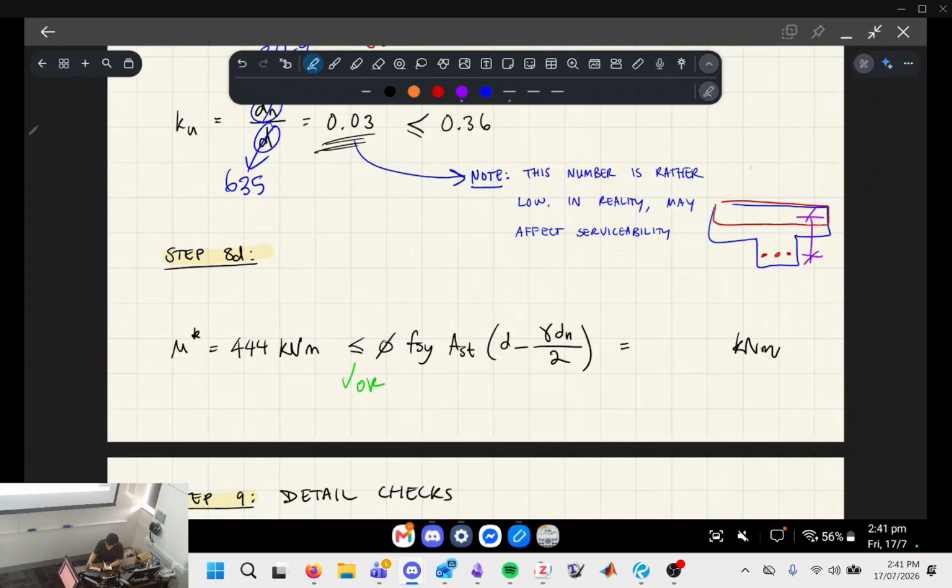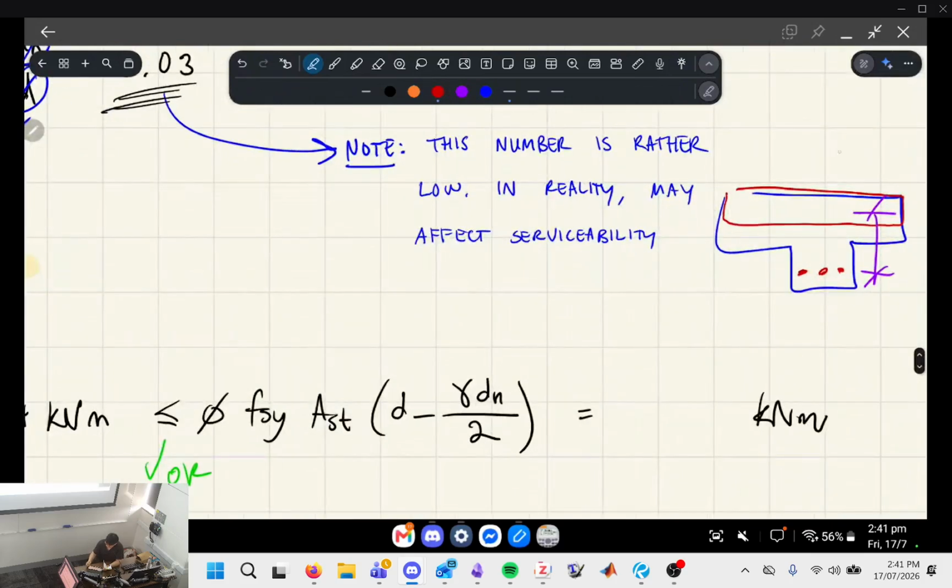So the idea is, I don't know if I'm over-explaining this, there's a force going in and out of the page there and there for the compressive concrete and the tensile steel. We have some kind of lever arm. So what we're doing to find the moment capacity, phi Mu, is phi multiplied by Ts multiplied by that lever arm.